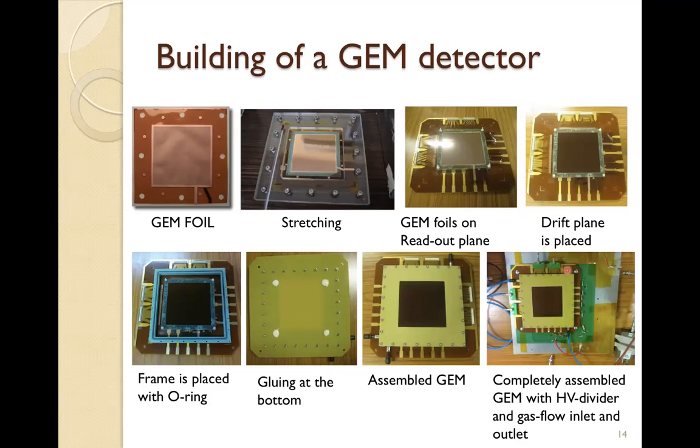These are some electronics boards where you can see the connectors here. In the readout there are actually a large number of pads or strips for collection of signal, but for the prototype chambers where we do routine study or some basic R&D, we sum all the connectors and take 1 signal from each connector.